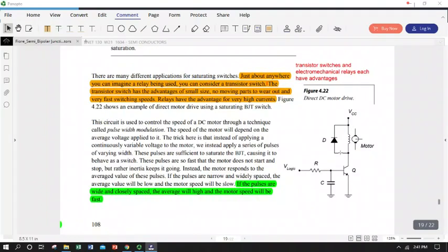Okay, another neat example of using transistors is switches. Remember, they're great for allowing little bits of current to control bigger amounts of current. So this is an example of almost a cascading three-way switch. We've got a really tiny current voltage signal coming out of a microprocessor. It's going to be applied to the base of our transistor, and when it is big enough to overcome the base emitter junction voltage, the transistor turns on and we flow a current from our supply.